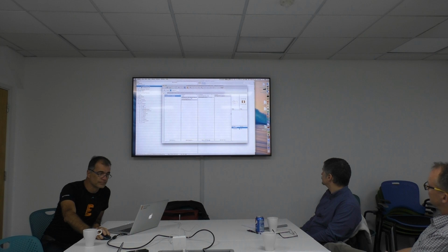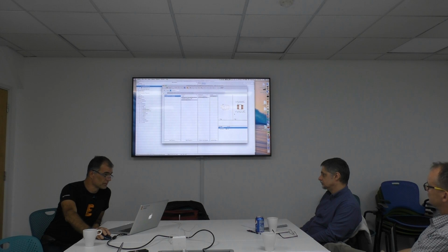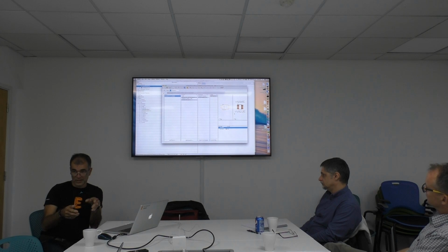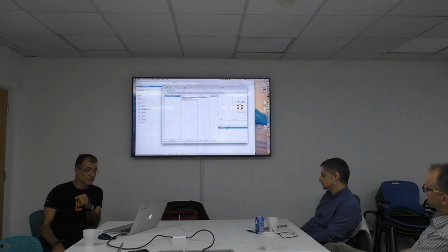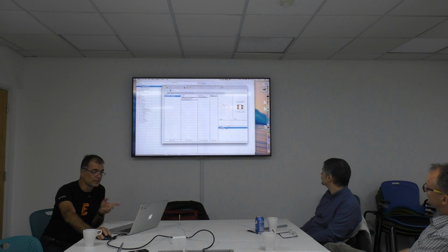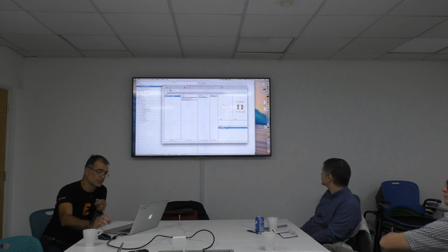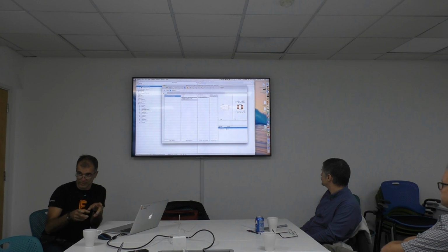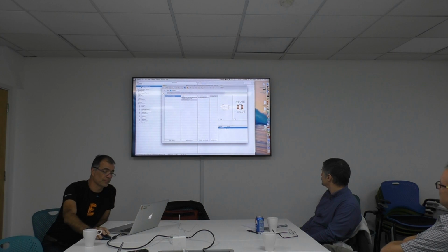so that Eagle knows, if I go here, for example, if I want to connect a net with this pin here, then Eagle has to know where to connect there in board, because you transfer the net information into the board. So this must fit. I looked into the data sheet of the manufacturer, and they say the input voltage goes to pad 5, for example. That's written here. That's what I have done here. So it's also important to remember or to name the pads correctly, place them correctly. So that's something you have to be very careful with.